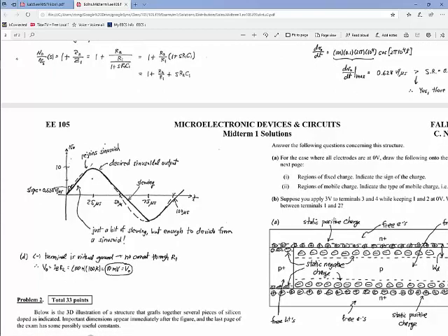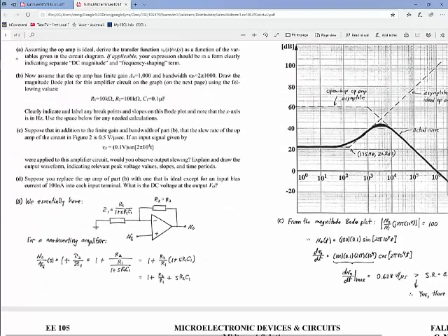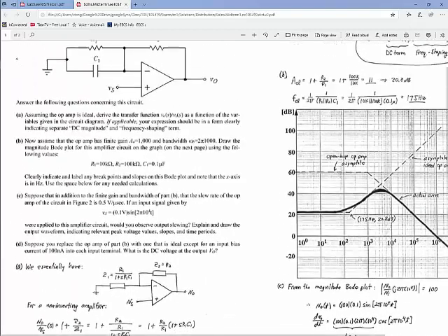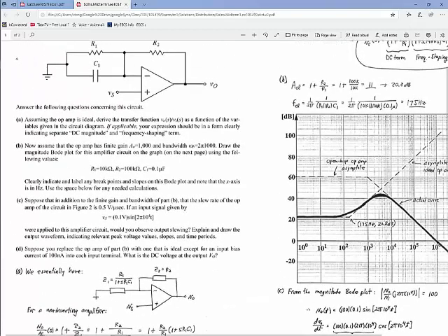Maybe it should have started out with that one there. But this is where you just put the current into the minus and plus terminals of this thing, and that current would not go through this at all because, well, let me go this. It will not go this way at all because that's virtual ground, so you got no voltage across R1. All that current goes out here, and you end up with this final voltage just being the current times that resistor R2. Okay, so that was the first problem.